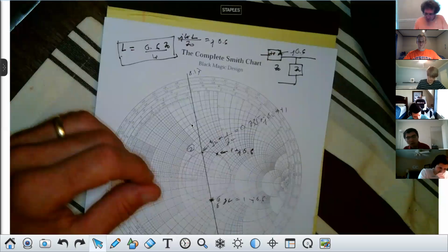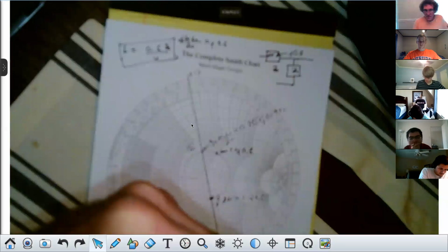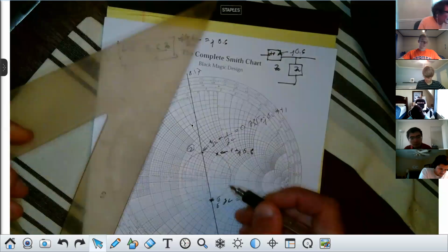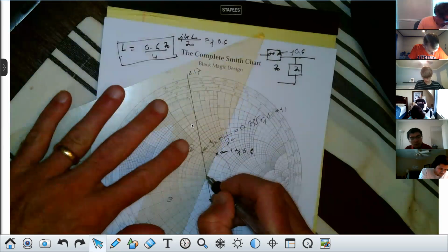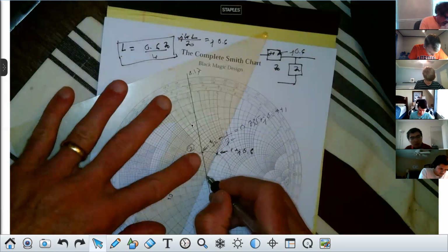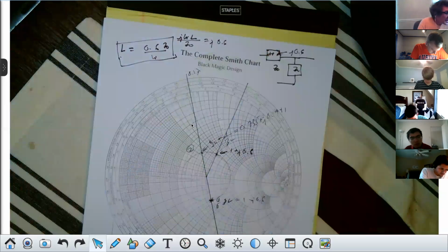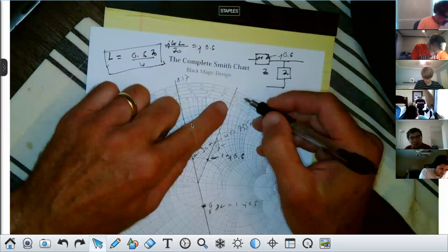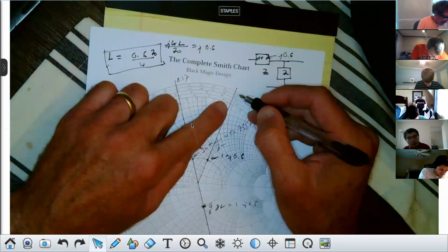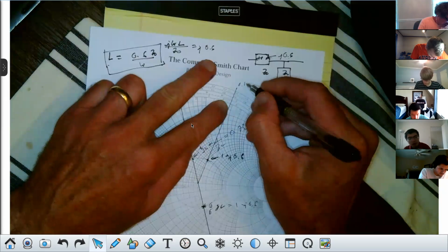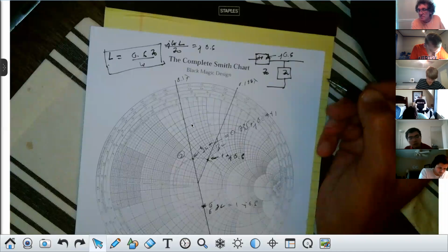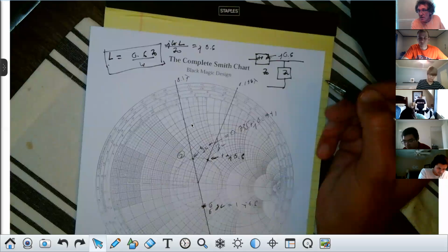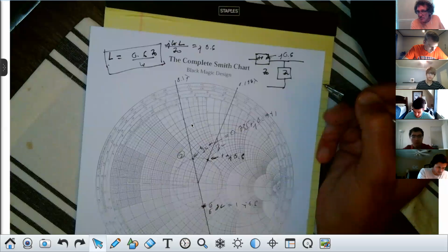All right, so how far do I have to move? Here I have to take my drawing triangle or straight edge, and now I go from the very center, and I hope you can see this. I do that, and I run it right through that point, if I can. And I have to flare the line and see what you get out here. I'm getting something just shy of 0.15. I'll call it 0.148 lambda. Take a look at that. Do you get about that? Everybody, can you all see that? And you have to have a good compass to do these problems effectively.